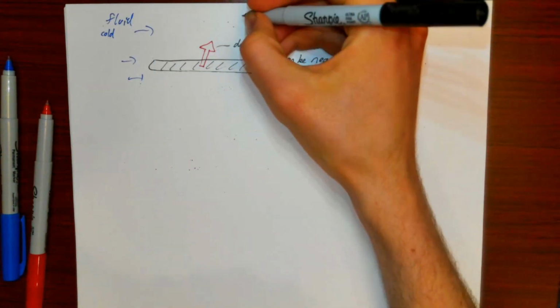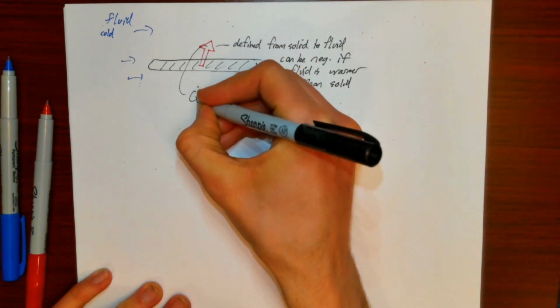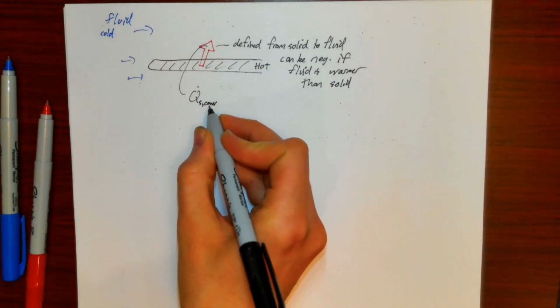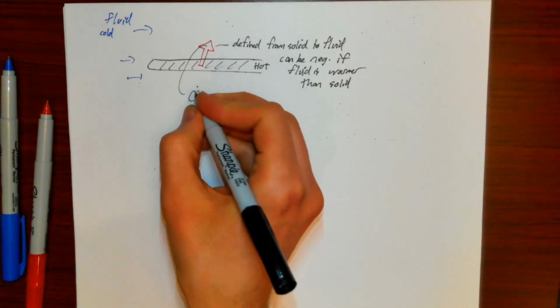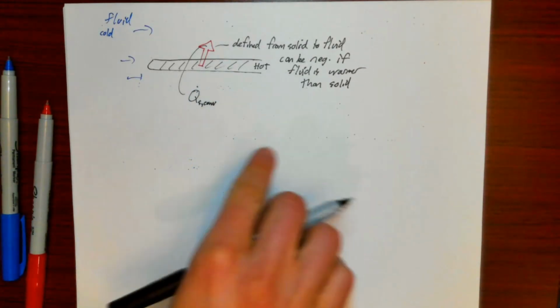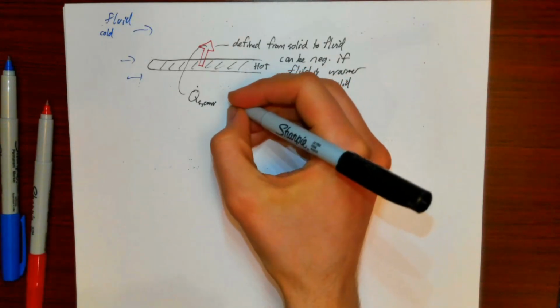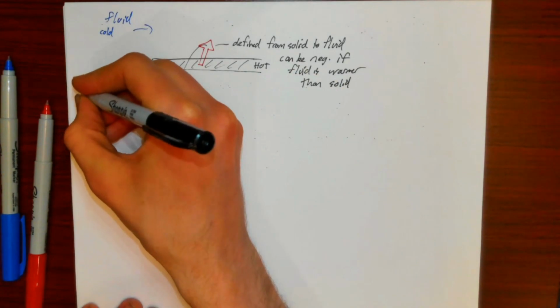We call it Q dot sub S, conv, for convection, S, and that it's a surface. It's a surface convection, to contrast it from the sort of fluid actually entering into and passing out of the control volume. So Newton's law of cooling